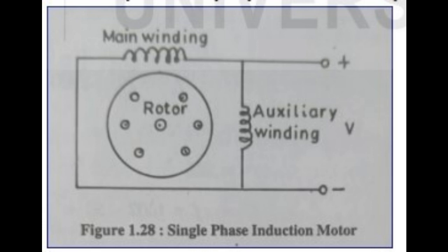2. Three-phase induction motor. It has three windings in the stator to draw current from the three-phase source. It has a wide range of speed but it is not self-starting. There are two types of three-phase induction motors, i.e., squirrel cage type induction motors and slip ring induction motors. Slip and frequency of rotor current of induction motor. When the three-phase windings of the stator are excited, the stator produces a field which runs at synchronous speed given by EQ 1.28.